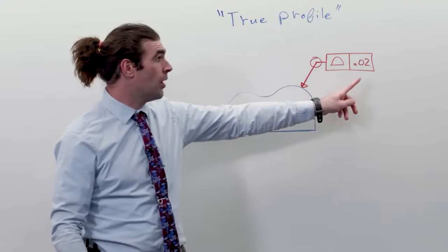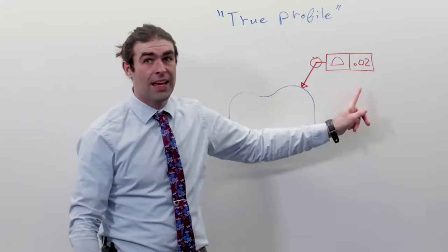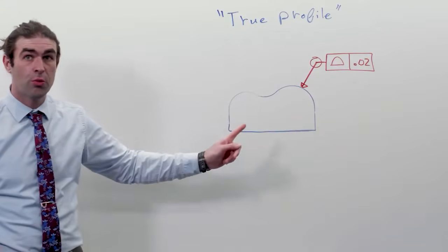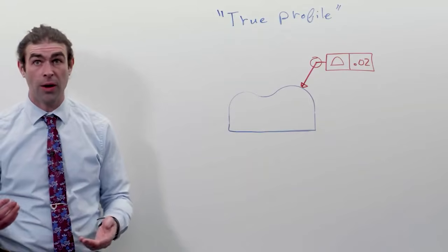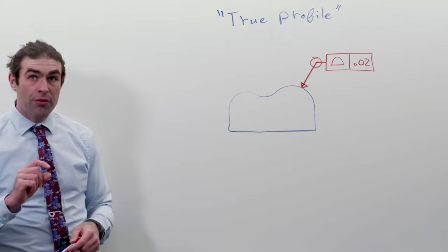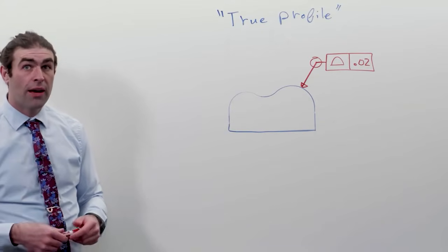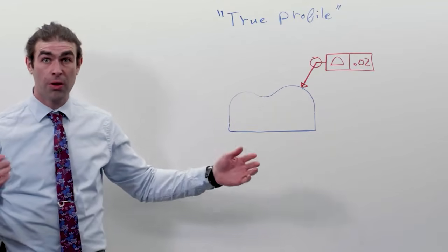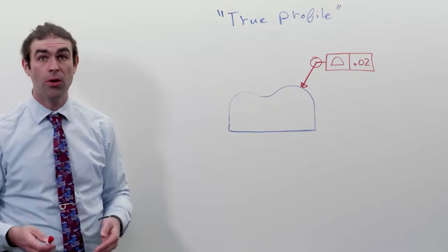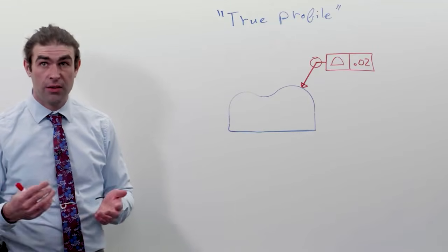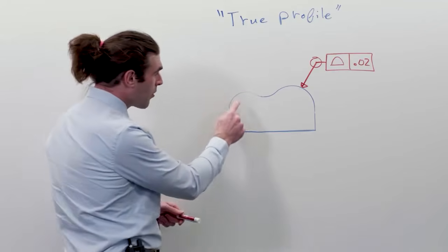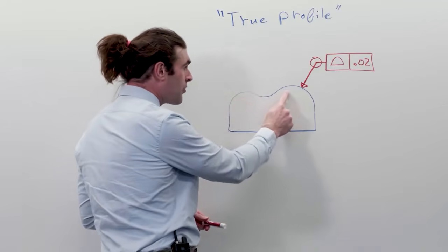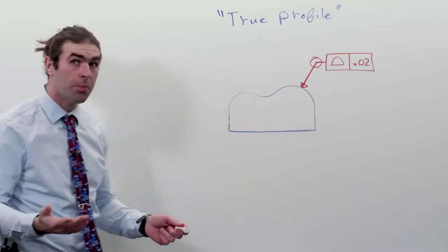And when it's an equal bilateral tolerance, aka the tolerance is split on the true profile, which is the default requirement, you've got half your profile inside and outside of the true profile. What I'm trying to get to is that the true profile is normally just the part outline, so the visible lines on the drawing. And then your tolerance zone just follows the part.